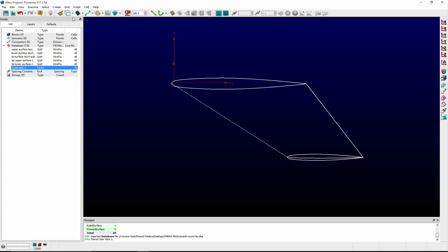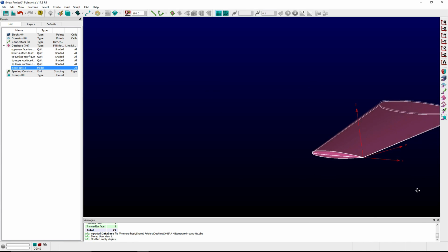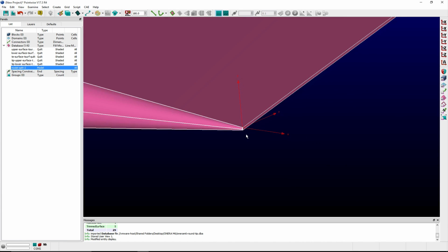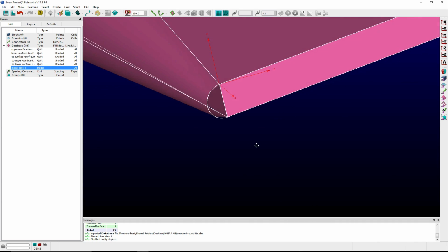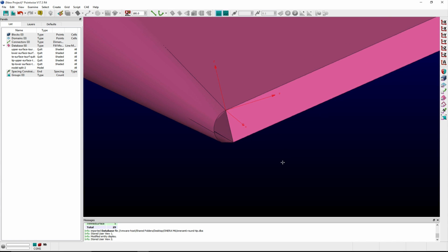To make this hole more visible, I'll toggle the rendering of surfaces from a wireframe display to shaded surfaces using the pull-down menu available in the toolbar. The missing surface appears adjacent to the finite trailing edge and perpendicular to the tip or wing cap surfaces as shown. I can quickly resolve this issue and create a watertight geometry model by creating a Kunz patch and associating this patch with the model.